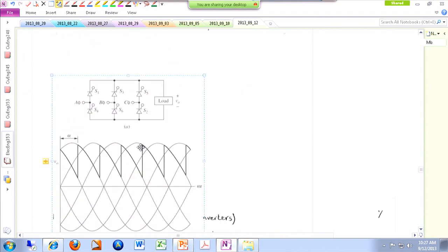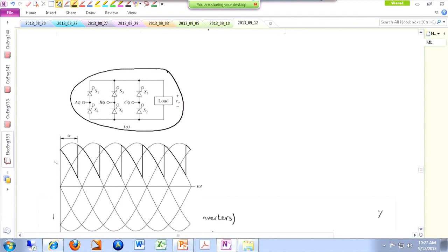Okay, so let's just focus on this SCR thing over here. All right, so we have 6 SCRs replacing our 6 diodes. Now it's called a controlled rectifier because then we can determine the firing angle of these SCRs. And as it turns out, maybe I can even use this figure over here. As it turns out, for instance, if this was a diode, D1, if we had a diode over here, this diode was eligible to conduct from here to here. All right?